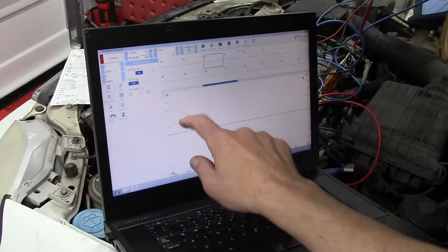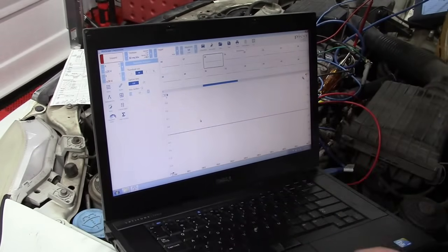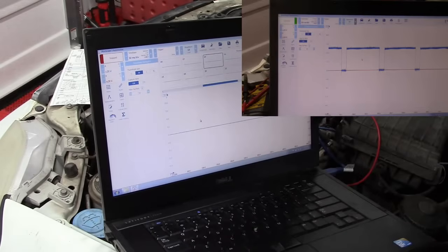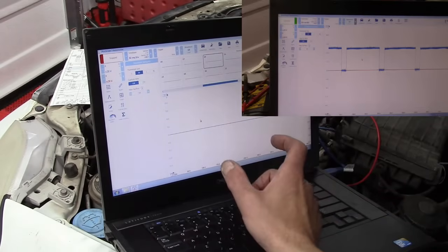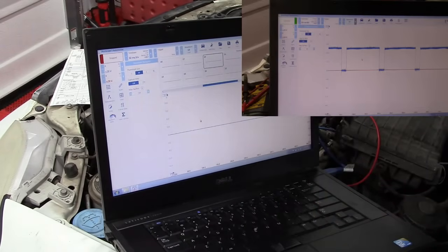But if you remember, our square waves had a much, much longer on time than off time. So that's going to skew that average. So out of that 12 volt on-off signal, you've got more time on than off. So this is going to be more like an 8 volt signal that we would see on the multimeter.